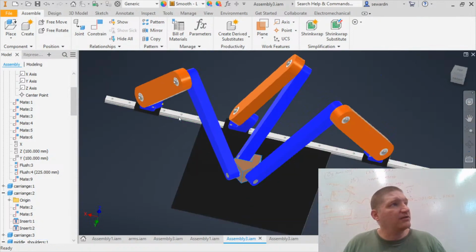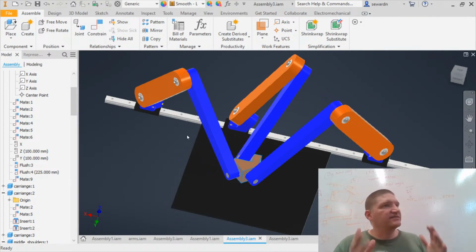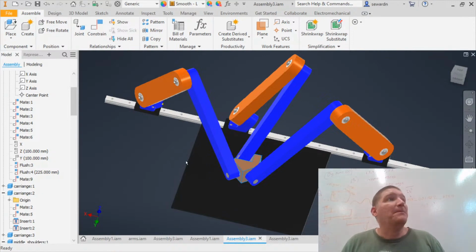right now I have 1 rail and I don't have it bolted to anything, but I can bolt that to an extrusion, keep it from twisting. So that's a big concern everybody has. Like, isn't that going to twist? Yeah, as drawn, it would be a big problem. It actually wouldn't be as big of a problem as you'd think, but might as well bolt it down to something. You bolt it to a table, an extrusion, whatnot.